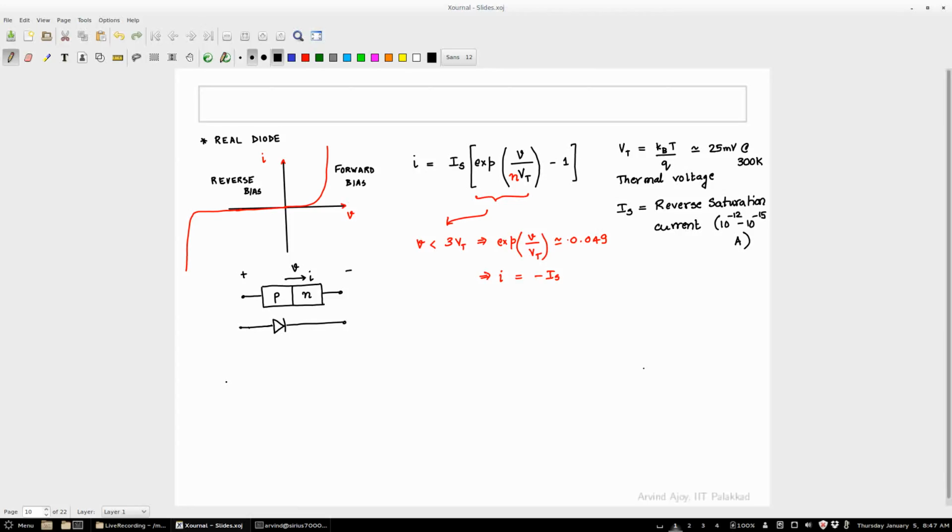Yeah. So, if you want to look at just the reverse current, what do you do? You choose a different scale only for the reverse region. And this is something which a lot of people get confused about, because if you look at the textbook, they say forward axis one scale, reverse axis another scale, and then at that junction it looks as if there is a kink. So you go back, look at the textbook that we have, you will follow what I am saying. Okay. So if I were to only plot the reverse current, right?